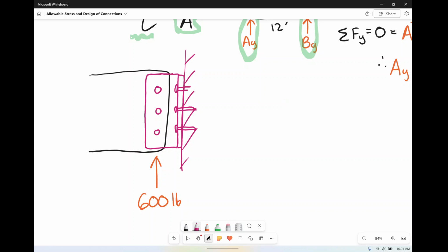So we've got nails that are going into the wood. That is our beam. And there's our force. And of course, there's our connections. So we're going to assume, and it's effectively for either one, that this is entirely fixed and not moving. So it is going to resist our force by going the opposite direction, right? Because it's not moving. So this is also going to be 600 pounds going the other way.